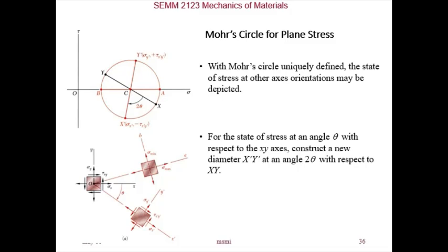So what we then have is, for example, if you look at this circle here, now this is your reference, that's the x-axis, right? A is the maximum value of principal 1, so there is sigma 1 or sigma max. From here, you go up or counterclockwise, that's 2 theta p1. And so from x, you go counterclockwise, theta p1, and you will get the stress element where you have principal stresses only. So you have sigma max, sigma min, okay, and no shear stresses.